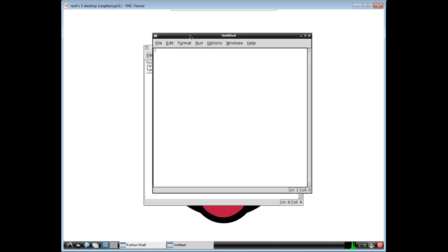Start off with the header text, letting it know it is going to be utilizing Python. You notice it starts off right away because of the pound sign. So where Python is located, and then start importing some of the modules. Also, Python is case sensitive, so this time and this time are not the same. This will error out, whereas this will not, because the module is called lowercase time, not capital T-I-M-E. All right, let's bring in the GPIO.